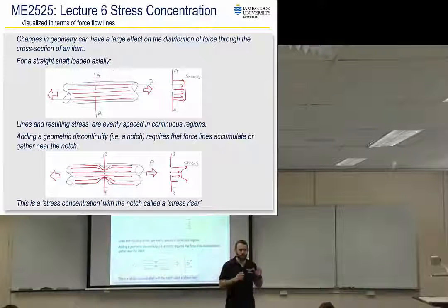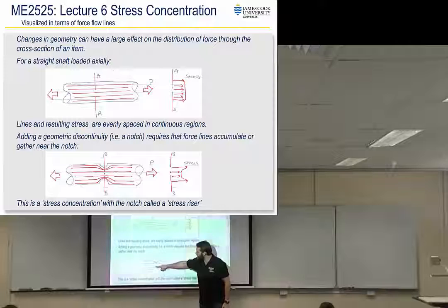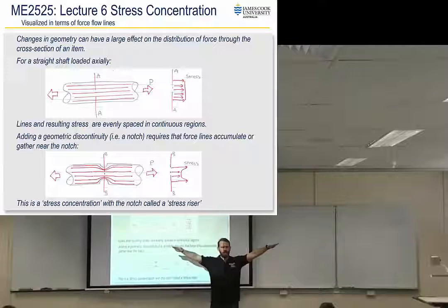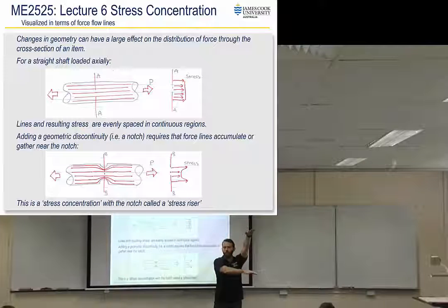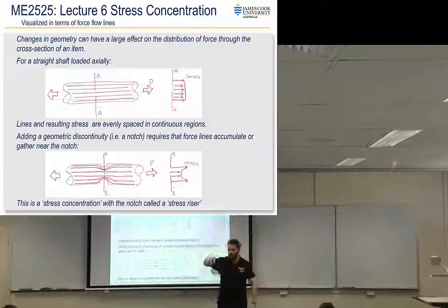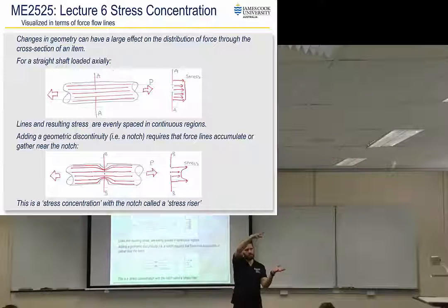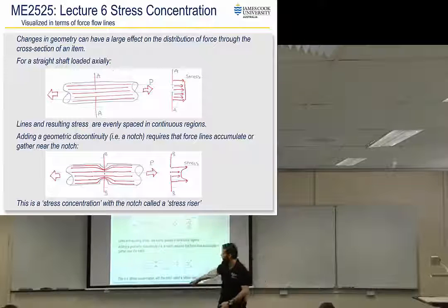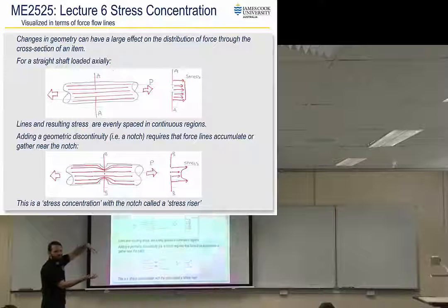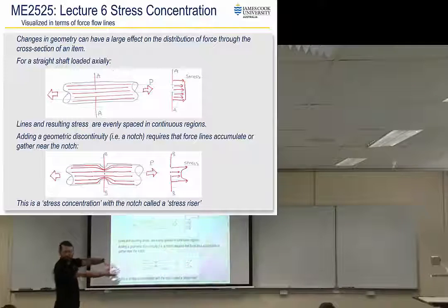In a perfectly ideal world, you are going to have more stress here, and so forgetting about the way that the notch works, we have to calculate stress on that area. Now, if you have enough of a transition from the wider to the narrower and back to the wider again, or just narrower if you've got a step down, enough of a transition, the atoms on this side have enough room to fairly evenly transition that force into the atoms to the right.